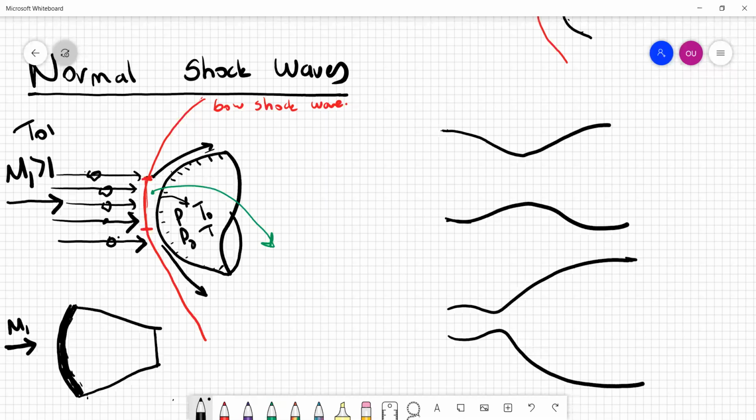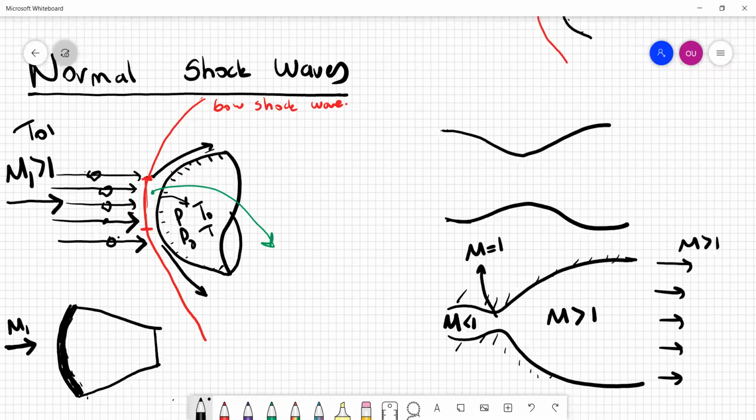The thing is, the incoming flow generally is subsonic in these kinds of geometries. If we talk about this rocket engine, for example, at the minimum area location, generally it becomes sonic, and then after this, it becomes supersonic. So the jet exiting from a rocket engine generally is supersonic. The thing is, under nominal design condition, it is like that. But during the startup of the engine and during some operational conditions, while the rocket is accelerating towards space, for example, altitude is changing in a very fast manner, so the ambient atmospheric pressure is changing very quickly.